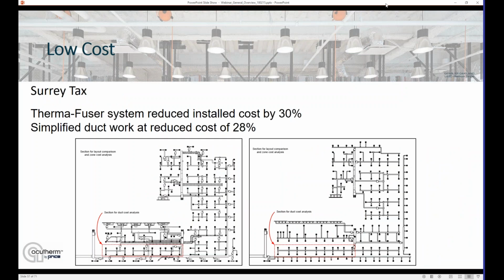I mentioned earlier the costs of the low-pressure ductwork can be a little bit more, but that's not always the case. Really depends on the orientation and layout of the building, just the geometries of the building. In some cases, and that's why I throw this example in, the ductwork can get a little bit less expensive, not because it's smaller, but because you can simplify it just by reducing the number of transitions, elbows, connections. So there are options there as well when it comes to the cost to have some savings in the ductwork.